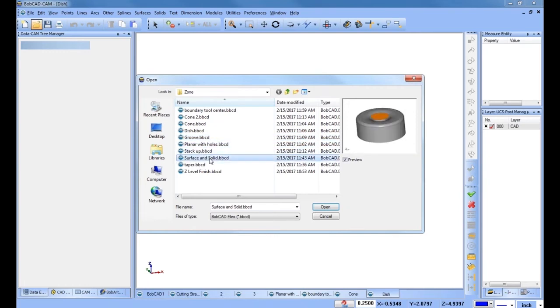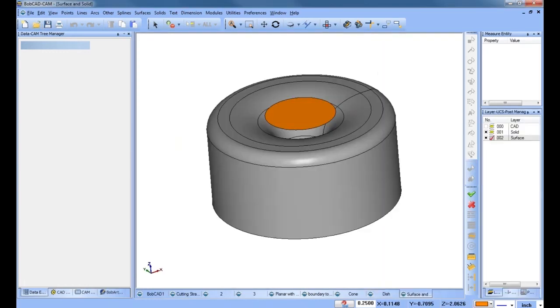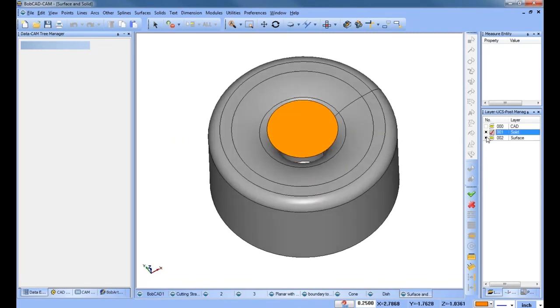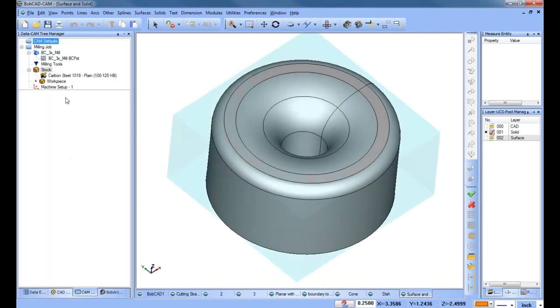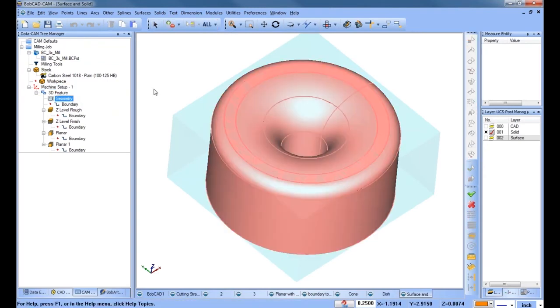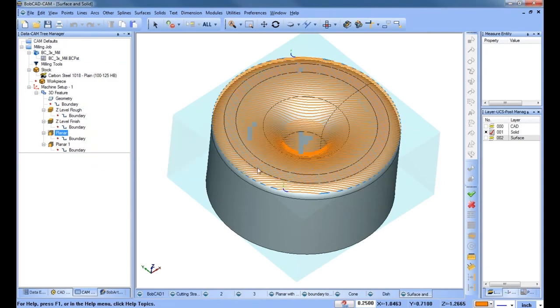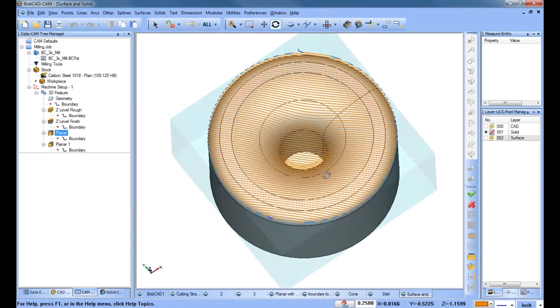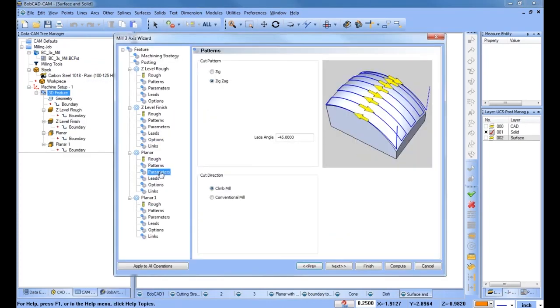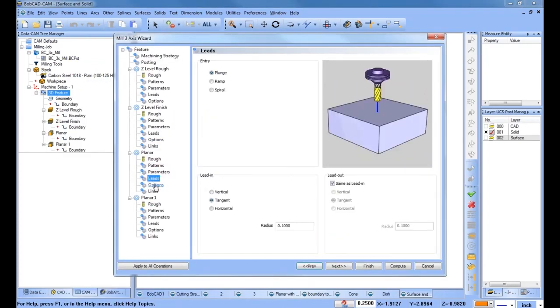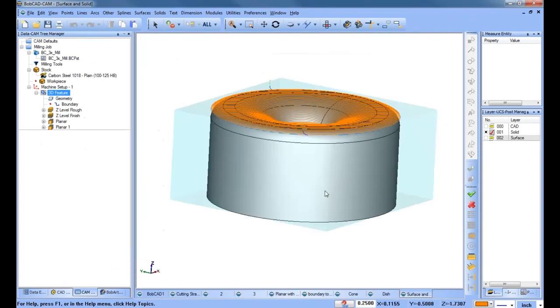Let's see this, we've got a stack up here. This is another good example of using surfaces to block where your toolpath goes. So we're going to do another job here. We're going to paste our feature and select all our geometry. Let's do our planar. Our planar is going back and forth over this model. Let's see if I have my depth settings here. No, it probably doesn't fit down inside of there.